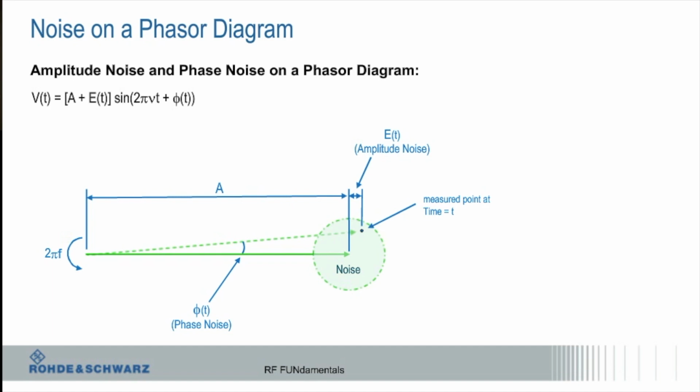A perfect oscillator would have no sidebands, no energy other than at that exact frequency. The reality is it has what we call phase noise. So basically there's energy that's spread out a little bit away from the carrier. So that extra energy is actually the phase variation of the carrier signal. So that gives you that rotate.